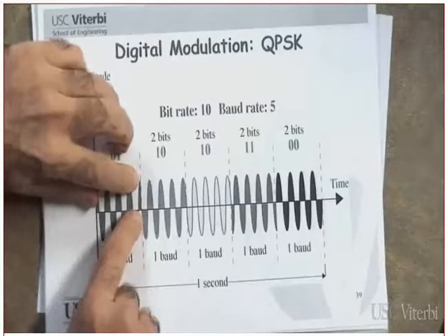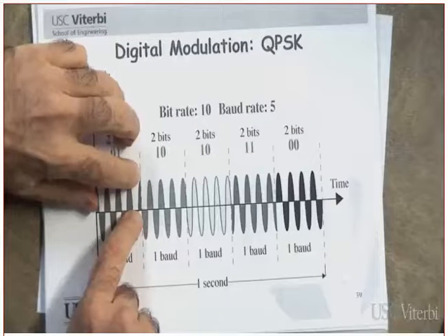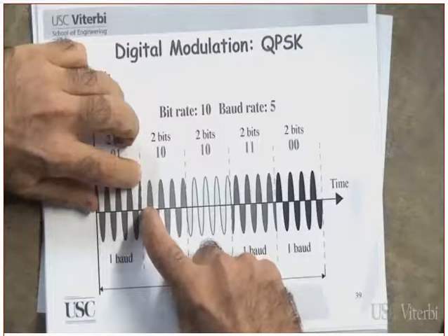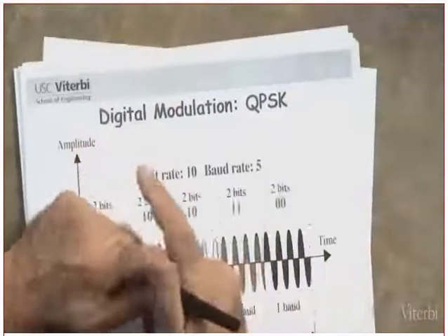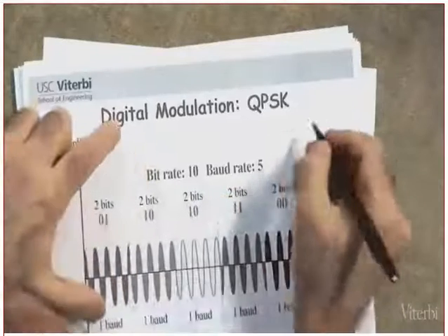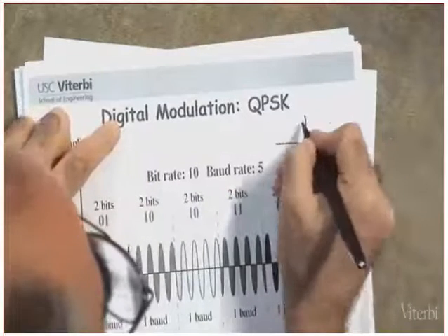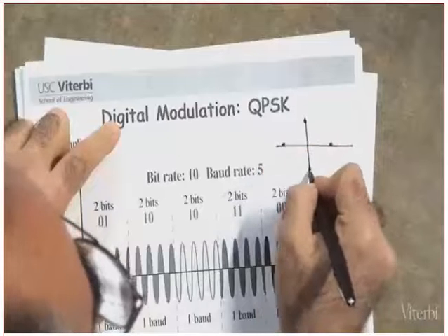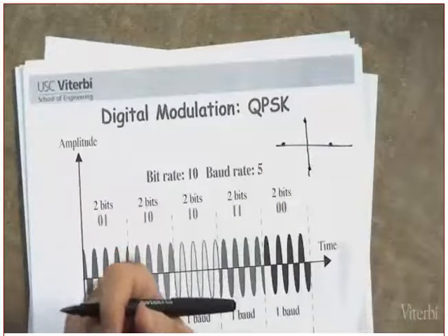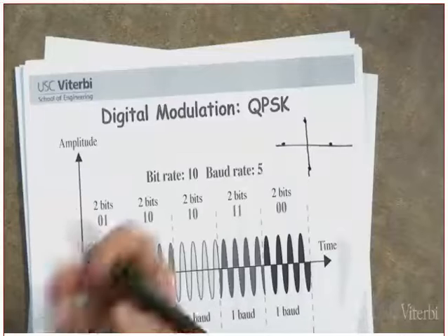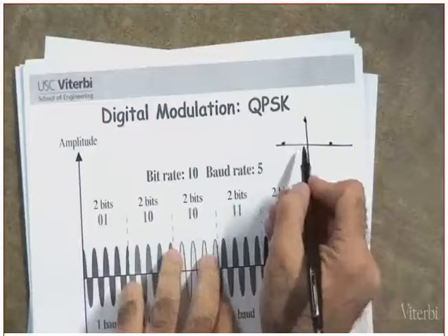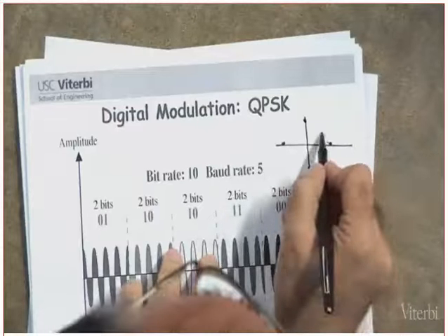At the boundary, what does the amplitude go from where to where? From positive to 0. Did you understand that or not? So at that point, by the way, have you studied constellation diagram? Yes. Signal constellation? Can you show it to me for the QPSK? How does it look like? Circle. One here, 4 phases. Question, are they on a circle? Why are they on a circle? Because the amplitude is what? It's constant. But you would say, Professor, you just said the amplitude is not constant. Make up your mind. At the transition from one symbol, where are these? These are on a circle.